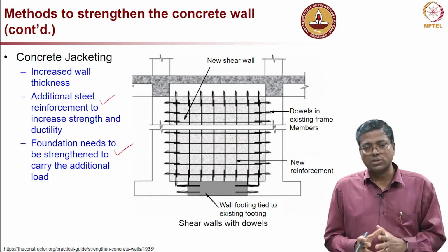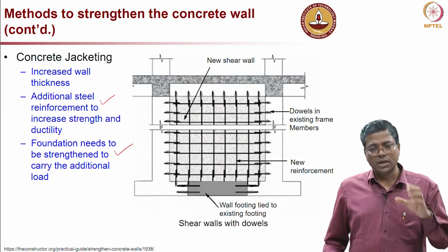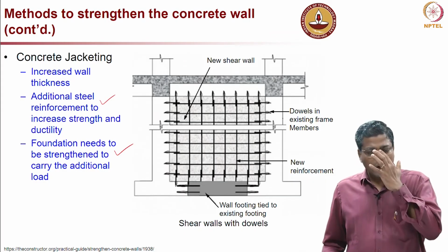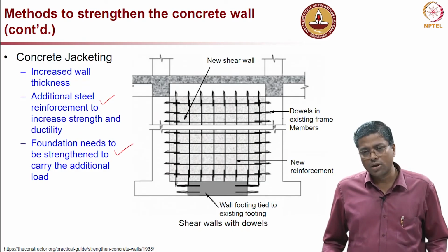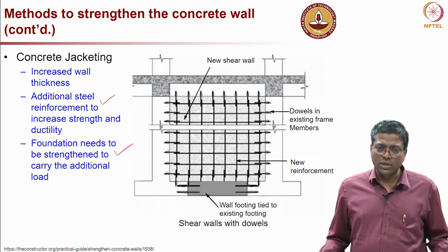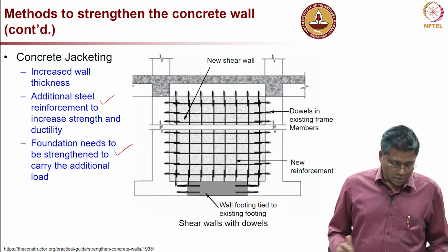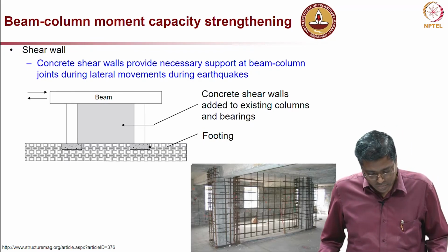If more weight is going to come, we have to also think about both in this case and the previous case, when you put more dead load onto the structure, you have to ensure that the dead load is also taken into consideration, and we have to check whether the foundation is designed sufficiently for that or not.